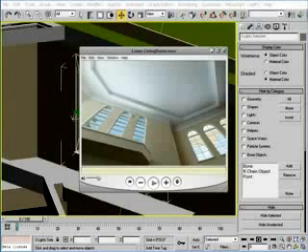So in this panorama, it looks like the same amount of illumination is shining all along the ceiling. It's probably not necessary to create three individual lights, but as a matter of rule, I like to take the few extra seconds to do it. It's not very time consuming, and it's usually just more accurate that way, because then I don't have to worry about how much light is coming in between the windows where there's really no window, instead of having a more accurate indication of light coming in right where those windows occur.